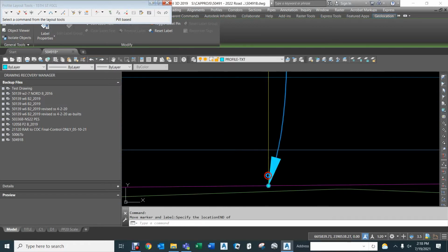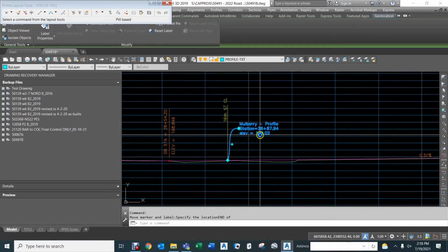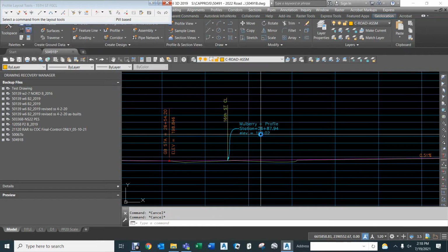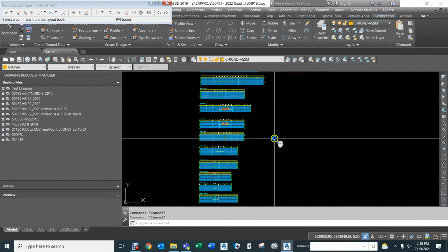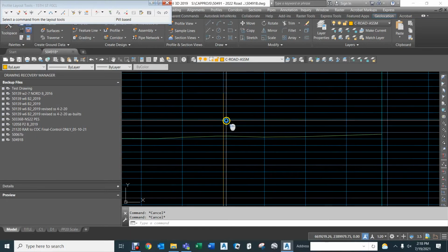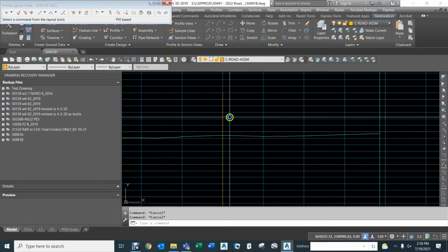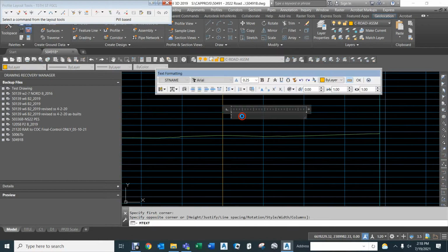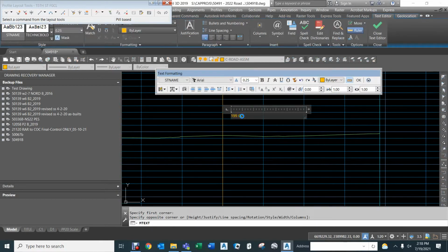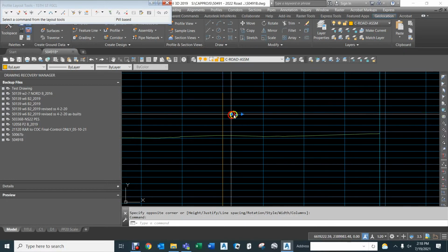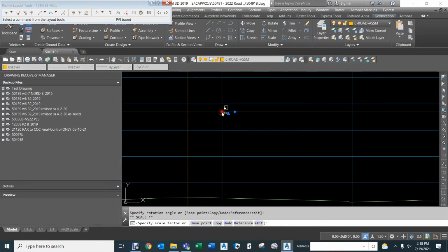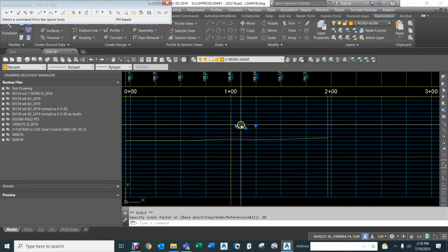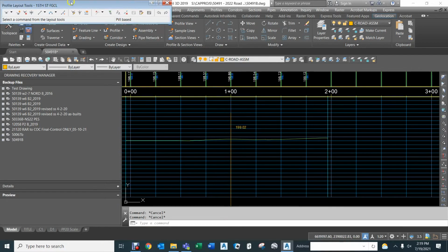So if we just place it right here, that tells us that it's 199.02 automatically. We don't have to recalculate anything. It's basically 199.02. So that's what our center line of our 16th Street has to be. So we go to 16th Street, we say it's going to be 199.02. If you want to, you can just put some notes in here and use these as you need to. Put little notes in here. So the center line has to be 199.02.